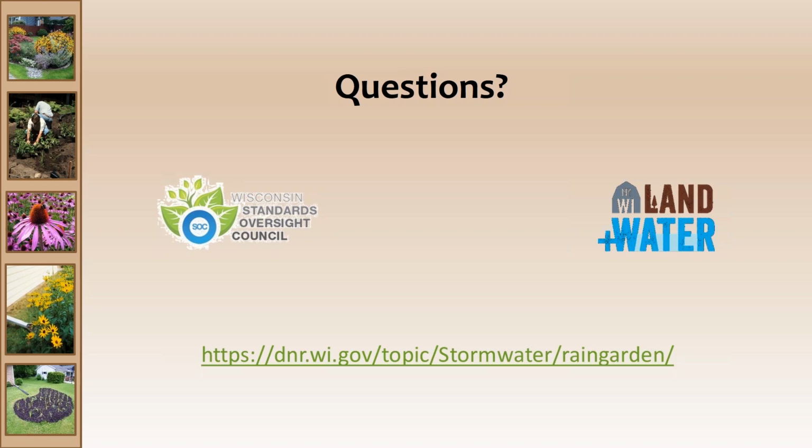Usually if a rain garden fails, it fails immediately. I've seen this over and over again, and it's for all the reasons that Perry's been talking about, compaction and so forth. So to restore the soils can be a challenge. I had one rain garden that failed immediately. The homeowner called and we went to the site, and it hadn't rained for at least 10 days. The rain garden was about 1.5 feet deep, so it's pretty deep, and the water was just standing in there.